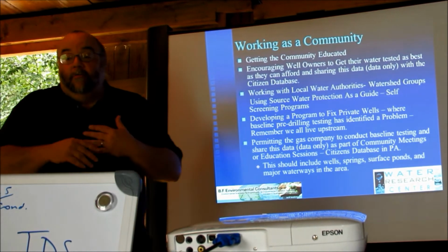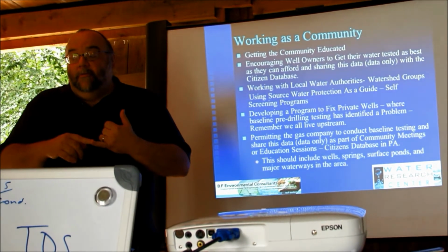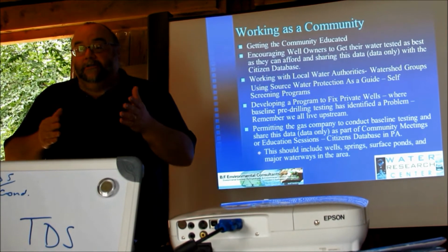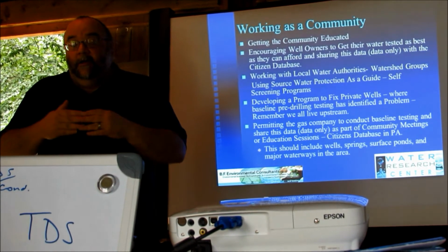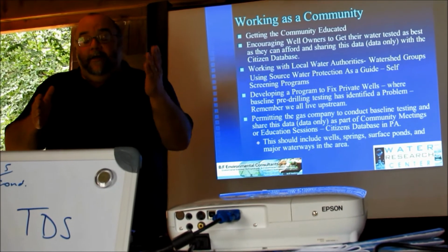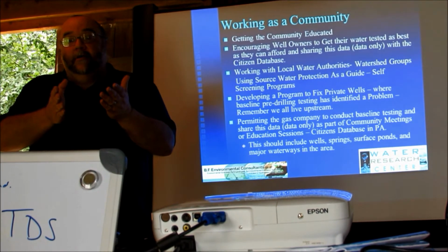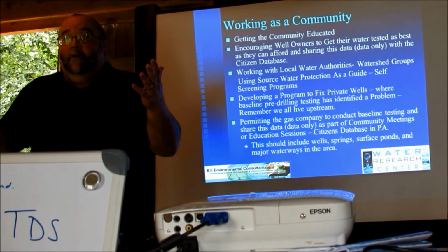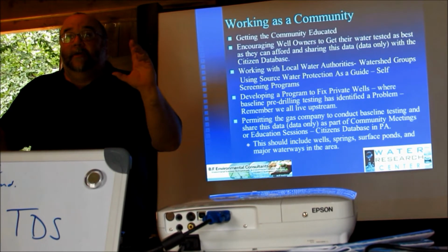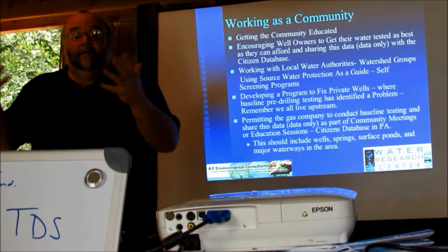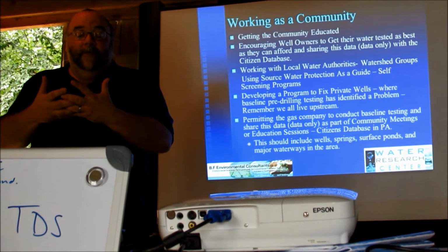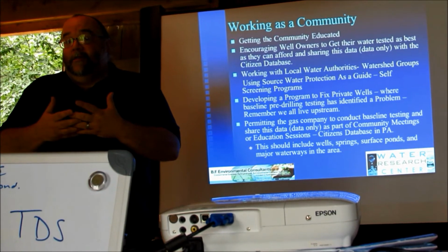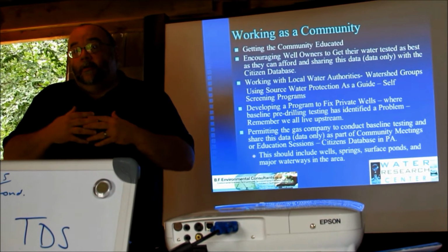High arsenic, most of the time, the first thing you want to check is if you have an iron problem. So if you have an arsenic problem and iron problem simultaneously, typically if you treat the iron, you'll take out the arsenic simultaneously, because as the iron becomes oxidized or transformed, the arsenic will actually go into the matrix of that particle that's created. So it'll be taken out simultaneously. And then how do you get rid of the iron? What do you do with iron?